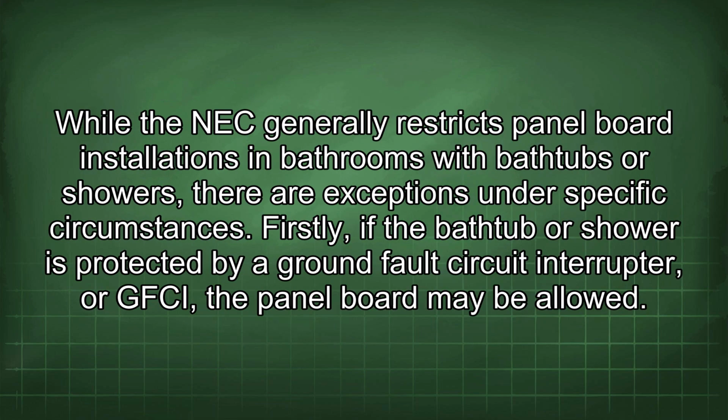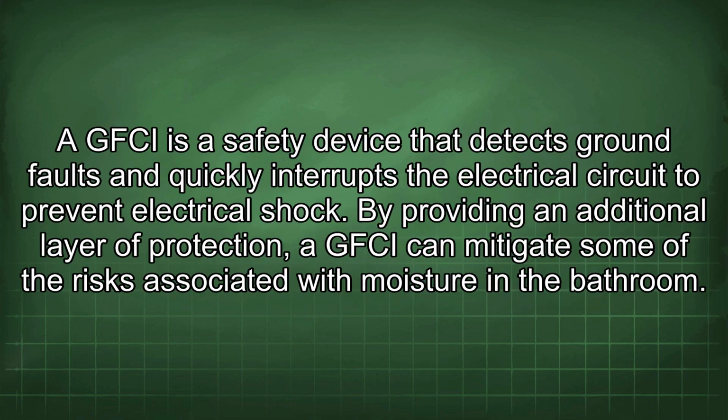While the NEC generally restricts panel board installations in bathrooms with bathtubs or showers, there are exceptions under specific circumstances. Firstly, if the bathtub or shower is protected by a ground fault circuit interrupter or GFCI, the panel board may be allowed. A GFCI is a safety device that detects ground faults and quickly interrupts the electrical circuit to prevent electrical shock.